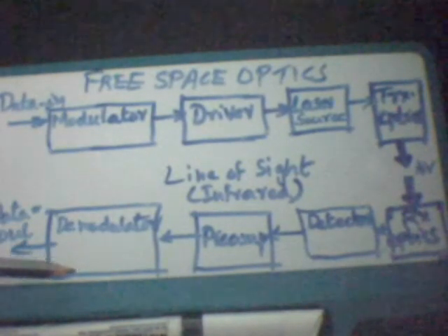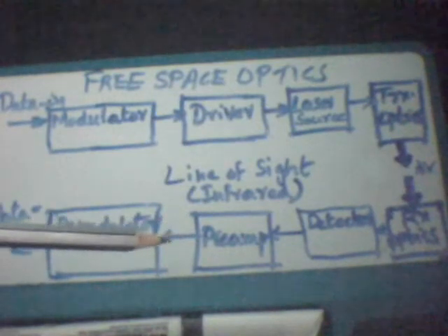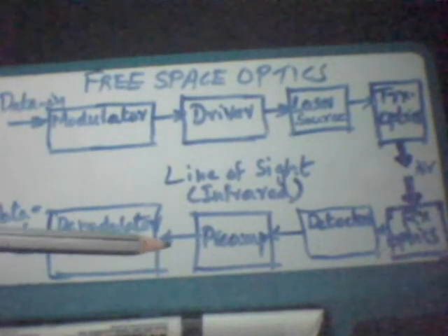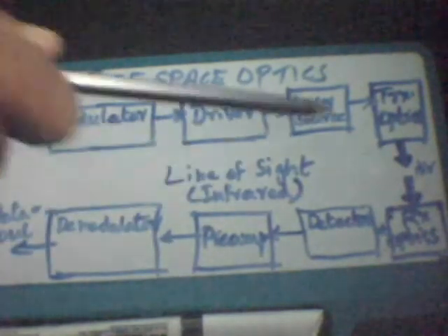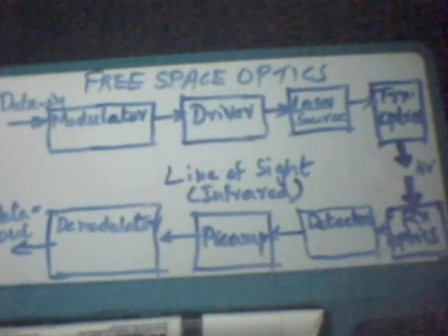The carrier used for transmission of the signal is infrared and is generated by either a high power LED or a laser diode. The basic principles for transmission of signal along the fiber are the same as for transmission through free space. Both involve conversion from electrical to optical domain and vice versa.